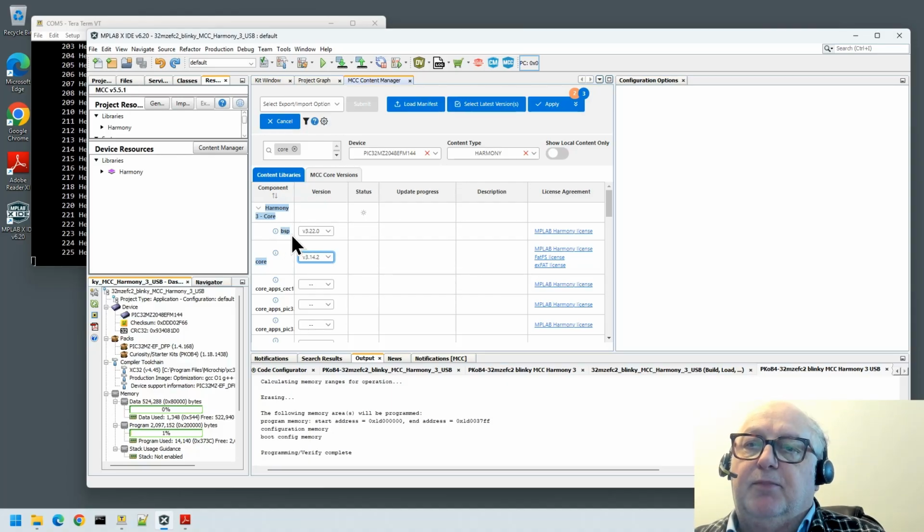This is the board support packages that Microchip provide for their boards, like the Curiosity board that we're using right now, but also for their other boards. I don't generally use any of the BSP functionality, and the reason for that is that in most real-world cases, your production will not be on a board with a board support package.